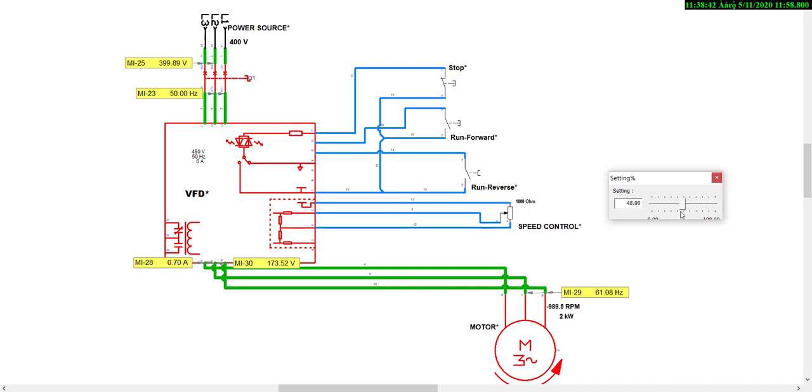When we're on 50%, you can see the frequency of the VFD supply to the motor is 40 Hz. Nevertheless, the input frequency is 50 Hz, but our VFD is able to supply 40 Hz at 200 volts. Now, people might ask me why the change in voltage. Yes, because the VFD works by sending pulse width modulation signals to the gate of our IGBT or MOSFET, and this is done by regulating the duty cycle.